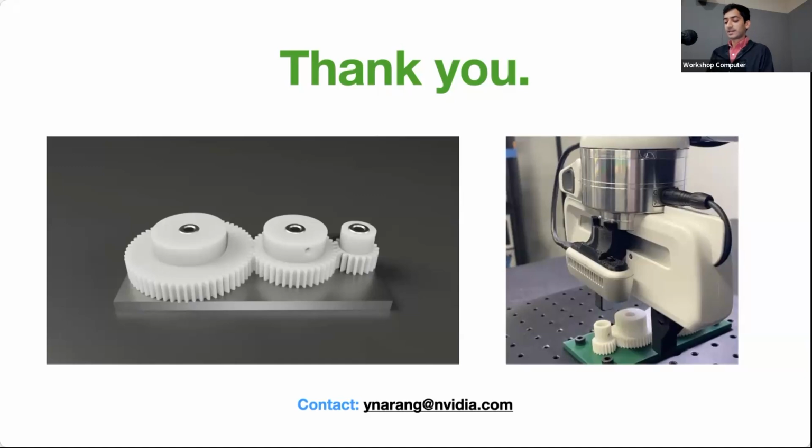Yeah, the good thing is that, I guess I didn't show it in this presentation, but there's usually very little tuning required for using this new contact formulation, the way that we've set it up. So basically, one prerequisite is that you have high quality meshes. If your meshes are, for example, poorly tessellated, you'd want to achieve fairly high element density in the mesh itself.